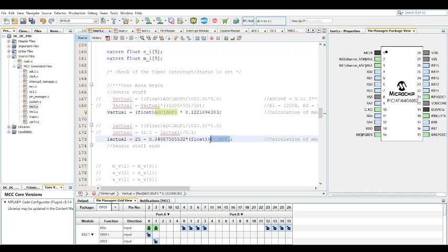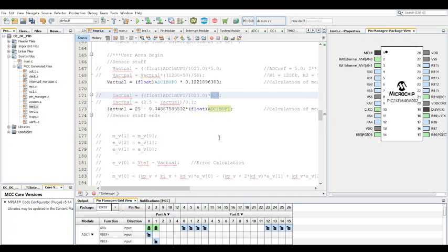You have to obtain that value, and if it's STM or TI, it's going to be 4095 over here, and 3.3 volts here, depending on which variation of those microcontrollers you're making use of. But essentially, this is how you obtain your actual voltage and actual current from your ADC readings, which, as you can imagine, is very important. It's very important to obtain these readings, because if you don't, there's no point in doing control.